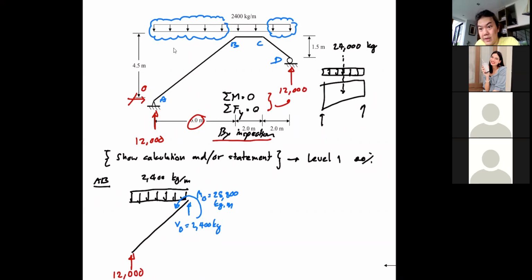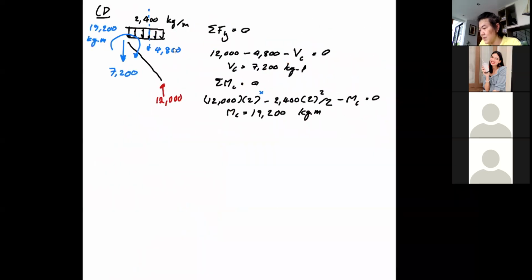By now, you should be able to guess that, in fact, you don't have to do anything. You have the forces at B from member AB, and you have the forces at C from member CD. If they come and join force and turn out to be in equilibrium, that means your member BC is complete. This is what you should pray for, right? They should come in together and provide equilibrium for your member BC. If that's the case, you are done.